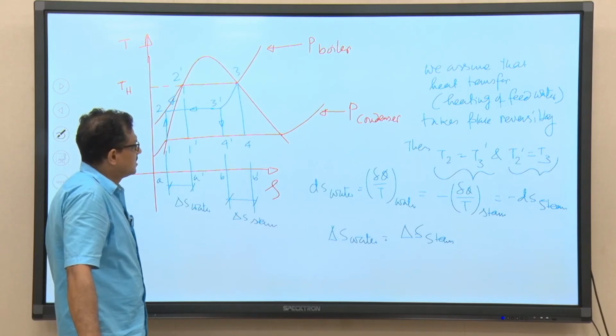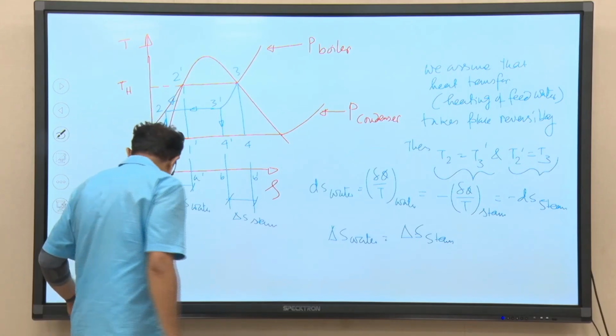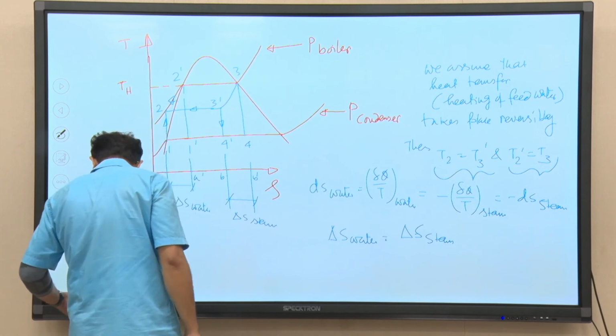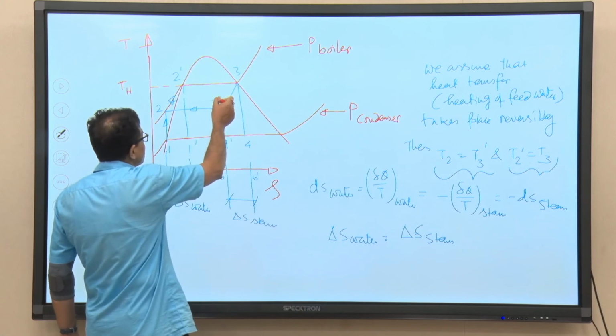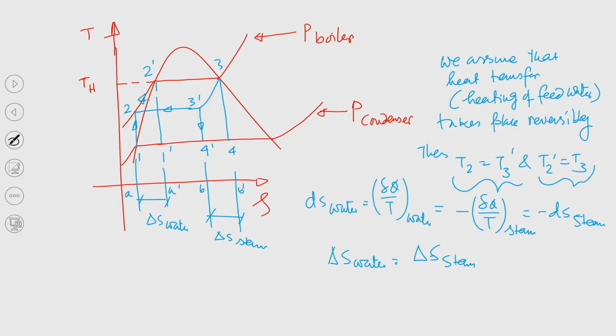Okay. So, this is the equation. Now, you can see after expanding, say the steam temperature will drop from T3 to T3 prime, the remaining expansion takes place isentropically, right. So, after this the remaining expansion will take place isentropically, that is 3 prime to 4 prime, right, fine.